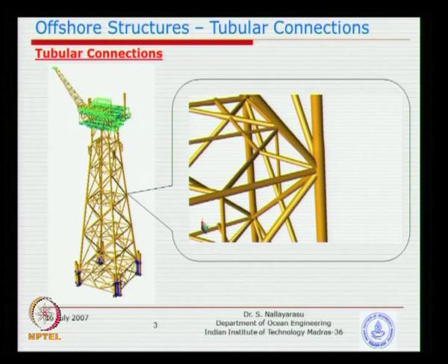That is where you will see that the design of joints becomes important. So the distribution of end moments or end loads will go toward the supports. Basically, wherever the stiffness is more, the loads will get transmitted. In this particular structure, if you look at the whole thing, where is the stiffness? Stiffness is higher at the foundation only, because it is a very simple cantilever, isn't it? So that is why, as you go down, more and more members will be subjected to higher loads.